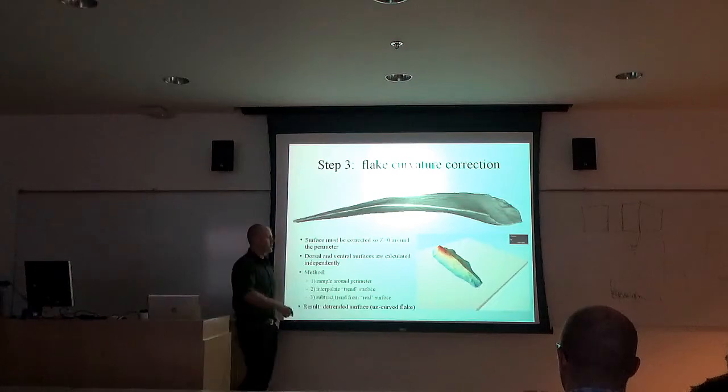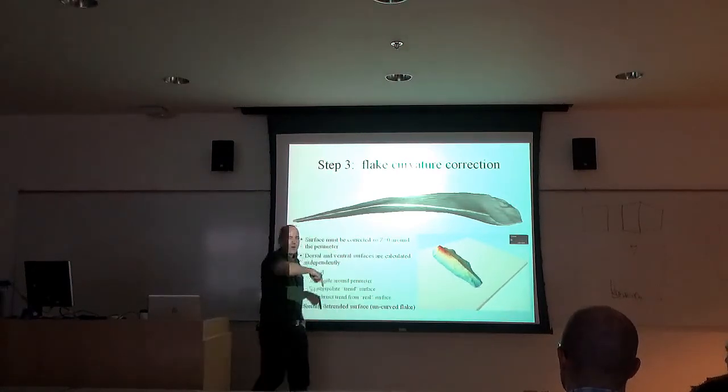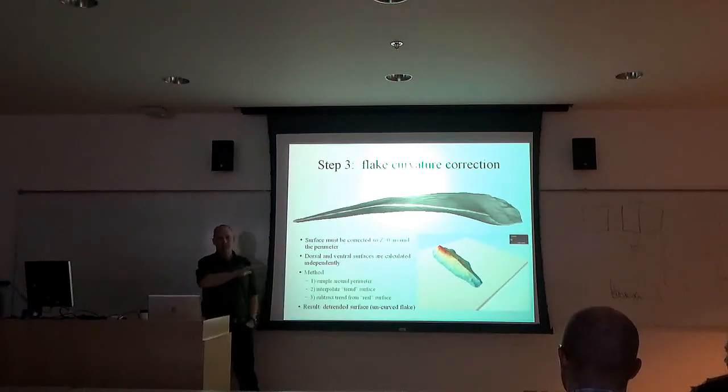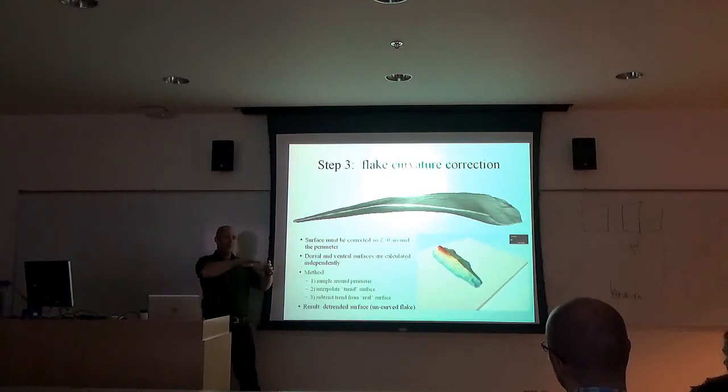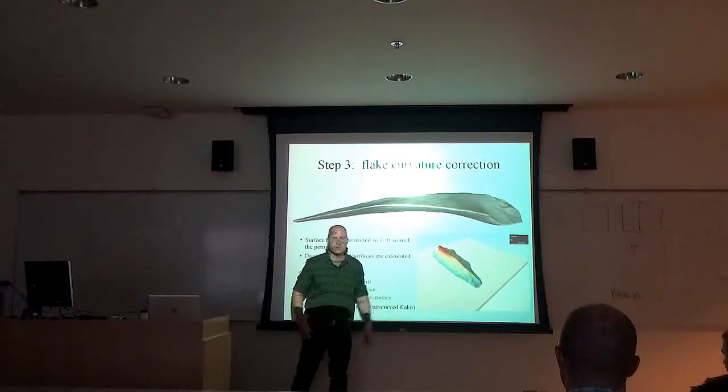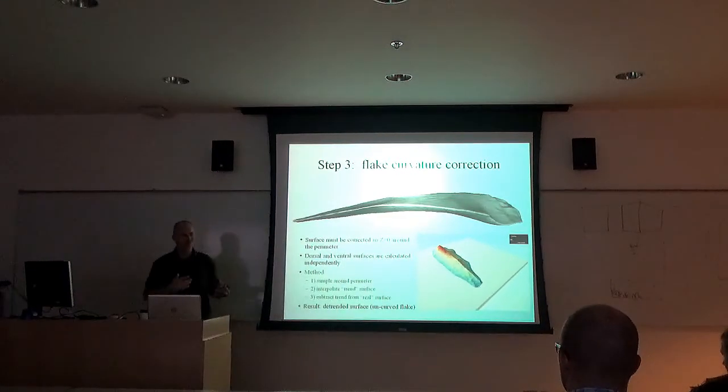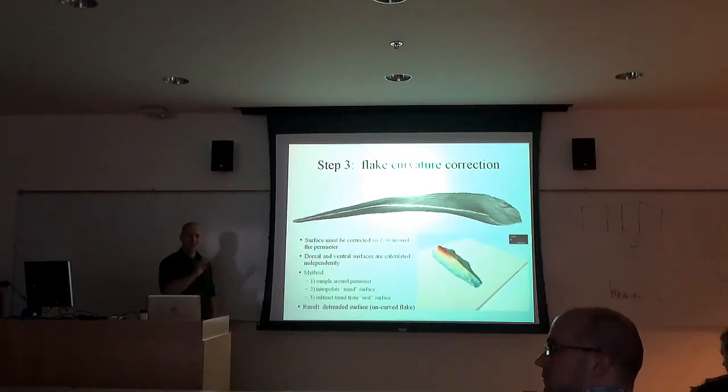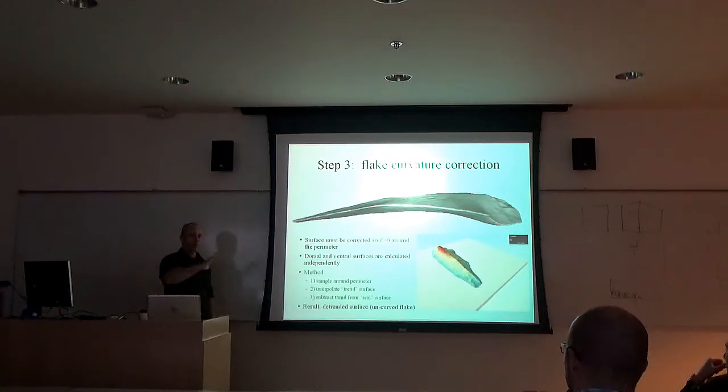You basically just sample a whole bunch of points all the way around the perimeter, interpolate a surface between them that's basically a surface that mimics the curve and any twists of the microblade completely, and then subtract from that. And it turns into this beautiful, flat, uniform blade where the edge is always at 0. So you're always subtracting to the edge rather than to whatever else.